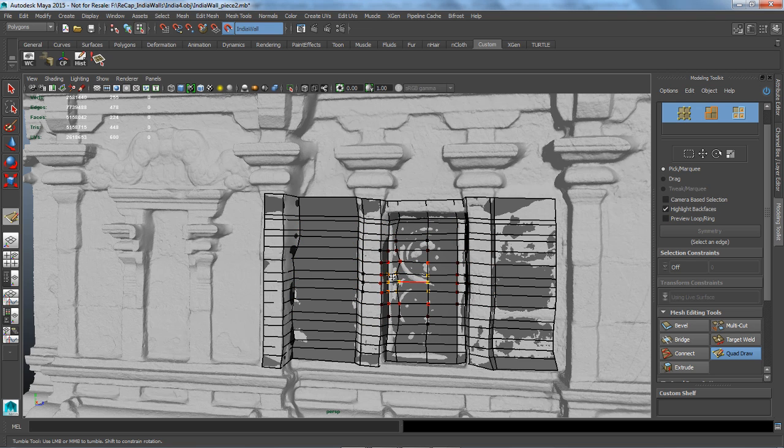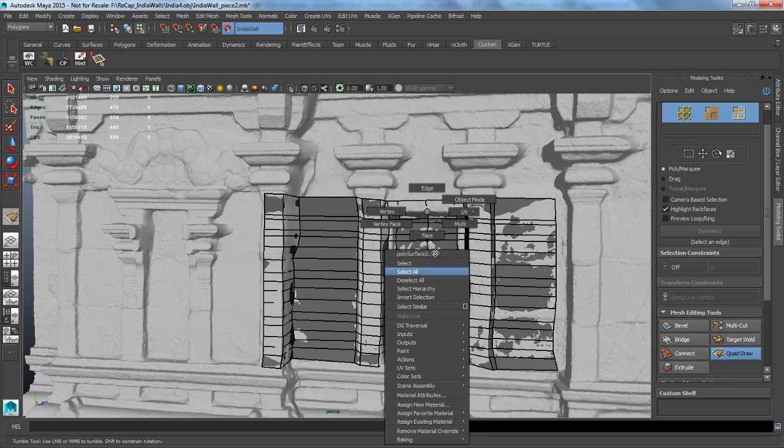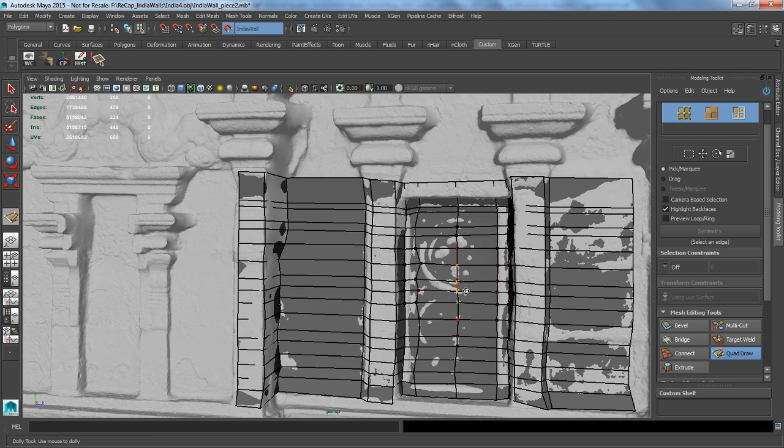You see how that is actually highlighting there. So if I grab all of these, it's going to grab that whole area for me. But another really nice way to work with this here is to be able to use the relax tool in here as well. So if I turn off my soft select, I can grab any of these vertices in here as I work, but I can also grab the relax tool. So if I turn on, relax works really well by holding down shift and then using the soft select there with the B hotkey for soft select. And I can turn that off at any time and hold down my relax.